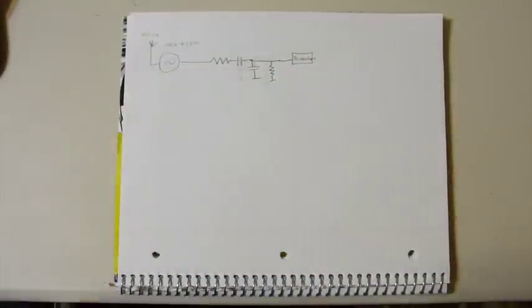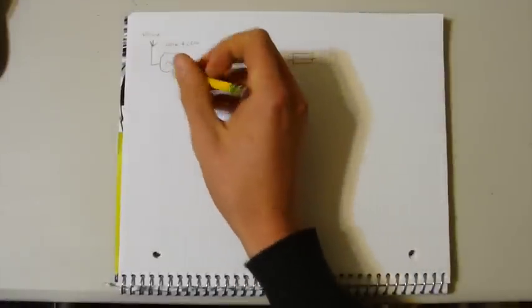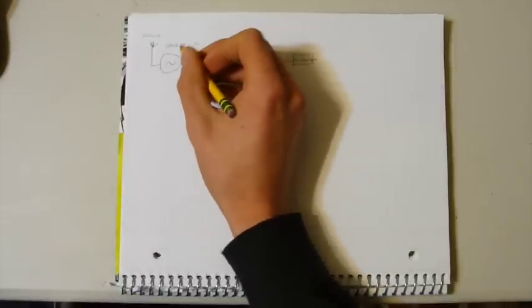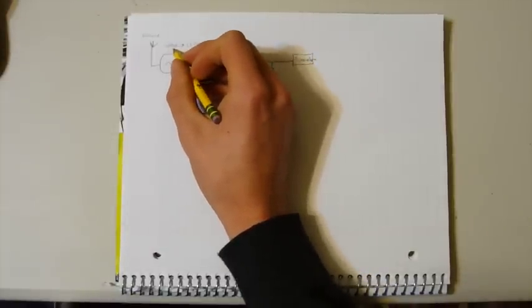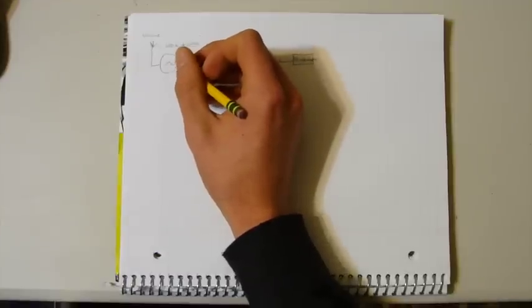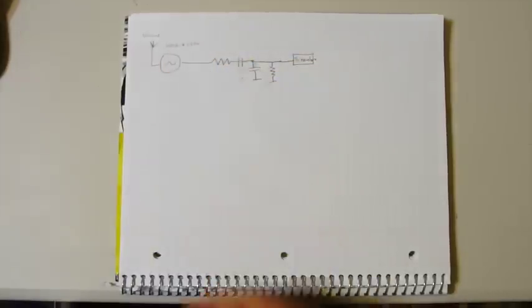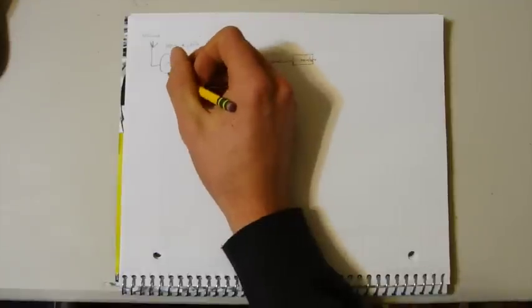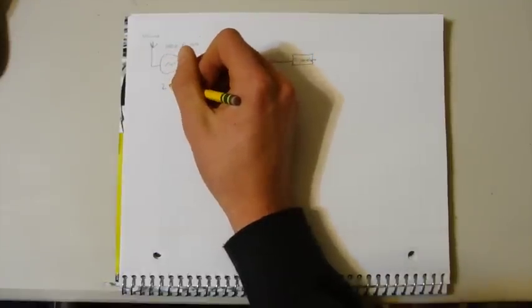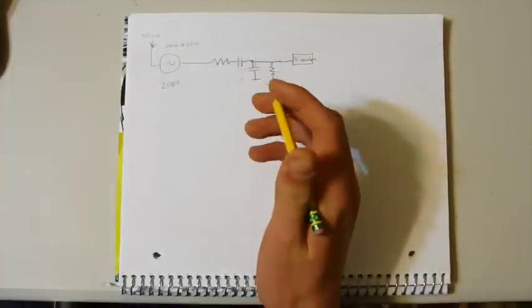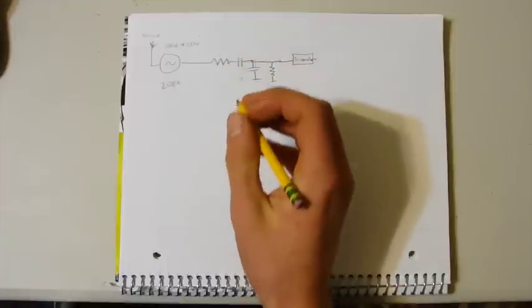Alright, so now looking at the volume part of the circuit, we have our volume antenna controlling this volume oscillator. Now, just arbitrarily, let's say the volume oscillator operates from 200 kilohertz to 220 kilohertz. And let's say that the distance we want to put our hand from the antenna gives a frequency of 208 kilohertz. And that distance you want to be the loudest. If you move further away, it'll become quieter. If you move closer, it'll become quieter.